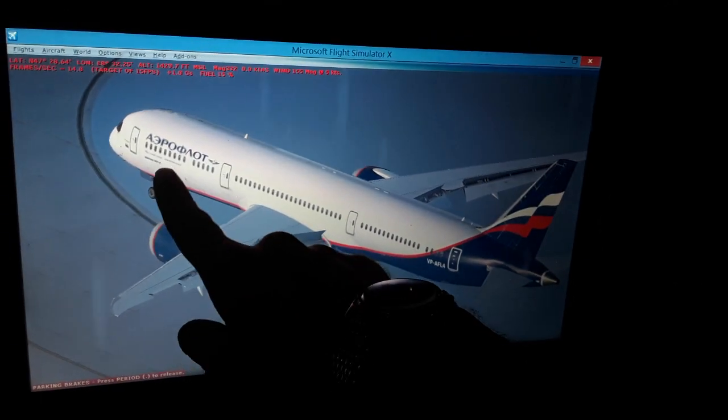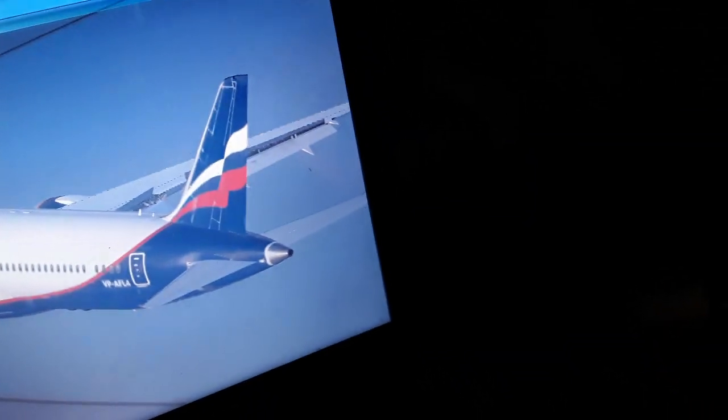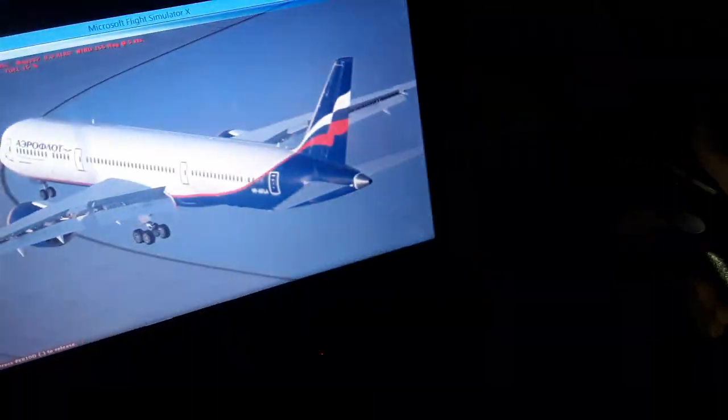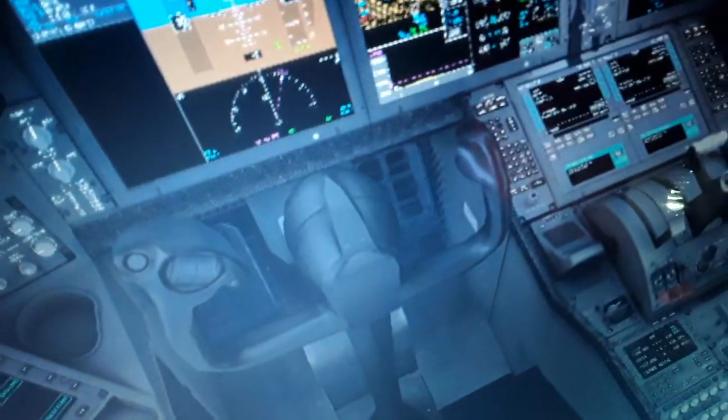You can move it, and also nose steering on the ground when you take off or land. So you move both in the takeoff and landing until some airspeed. So you see the rudder deflected using the rudder pedals inside the cockpit. We can deflect the rudder like this, moving the rudder pedals.